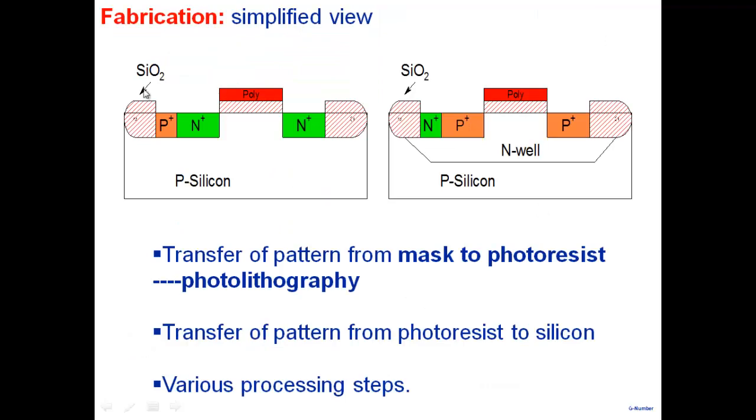So all right, what we are interested in is, how do we create an N-type MOSFET and how do we create a P-type MOSFET, let's say, to begin with. So note that for an N-type MOSFET, we are talking about a region of N+ here. These are source and drain. We need a thin gate oxide and a poly here. Polysilicon will act as a gate. Polysilicon is also doped. Okay, heavily doped N+ poly and P+ poly here. So these are there. And as I said, this P+ contact is needed to make a contact to the body, to the substrate here. Okay, so that's the substrate contact here.